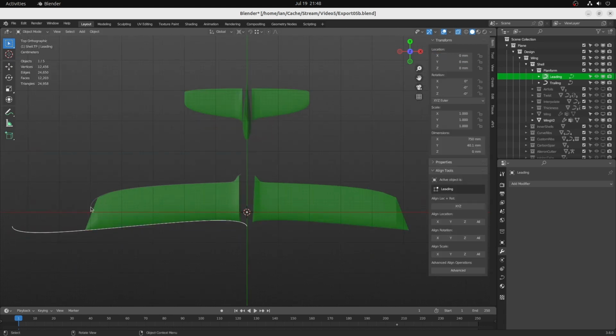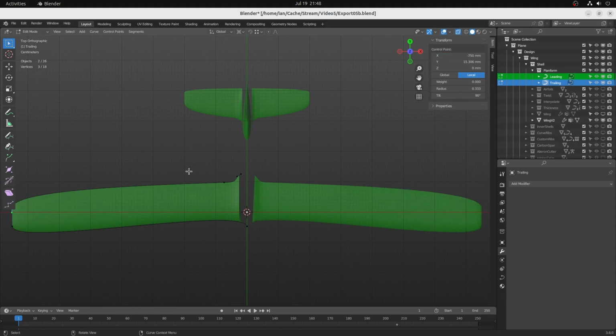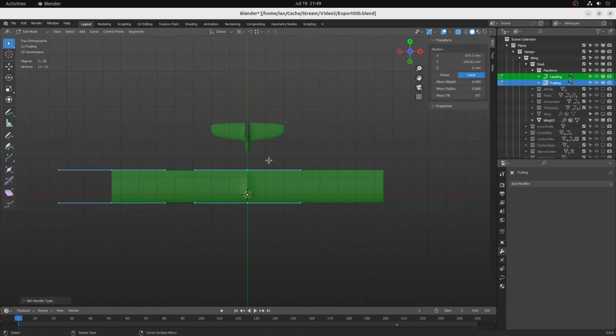The internet says that an aspect ratio of 8:1 is quite common for balsa gliders. Might be a bit high for 3D printing, but I'll try it. It gives me a wing area of 28.1 decimeters squared. The internet says the cubic wing loading should be under 4, and a weight of 500 grams gives me 3.3, so we'll try that.